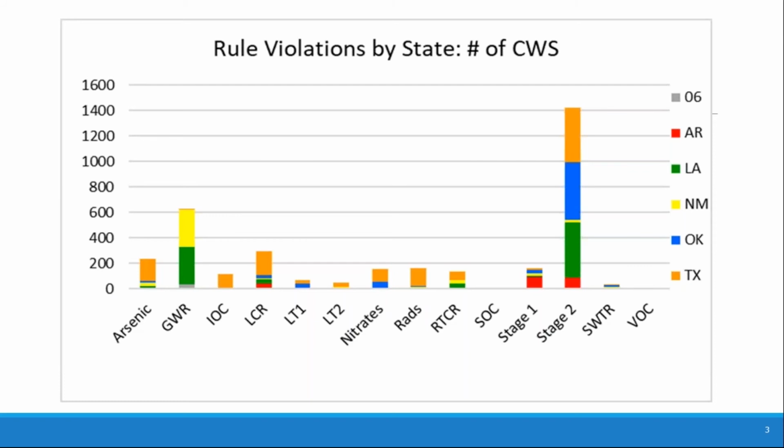We're at the bottom of the Mississippi River watershed, of course. So we get a lot of dissolved organic carbon in our water from many, many other states, in fact about 34 or 35 that drain into the Mississippi River basin. As a result, when we add chlorine to our water, and we have to have more than a trace in Region 6 because it's warm, we're struggling with issues in Louisiana and Oklahoma with Naegleria fowleri, and a trace disinfectant just won't cut it. We have to at least have 0.2, and in Oklahoma and Louisiana they strive for 0.5 to protect against Naegleria and other microbial pathogens.